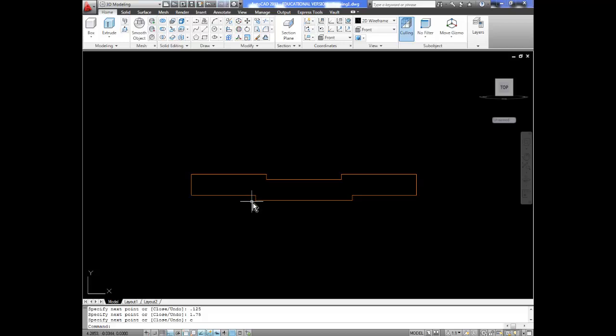Other dimensions are given to you in another section, and you should be able to print them to have them with you, or take annotations on a separate piece of paper, or do a sketch first. Now, to extract the 3D solid from this area, the easiest way to do it will be to convert it into a polyline to have a boundary set for this area.